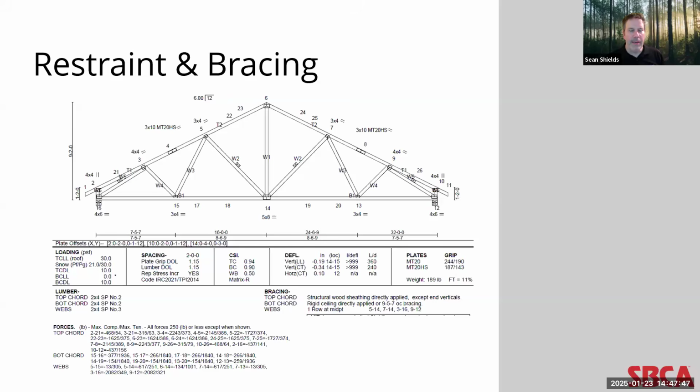So again, going back to that truss and those high compression forces that we were looking at, we see that that 316 web and that 912 web are under a high amount of compression. So this could potentially cause significant performance issues.